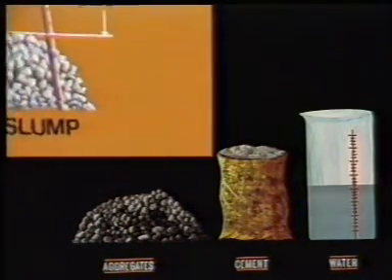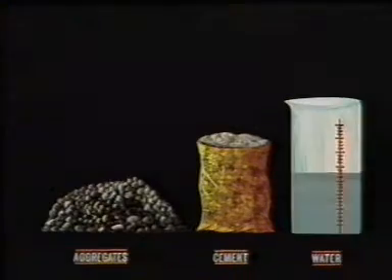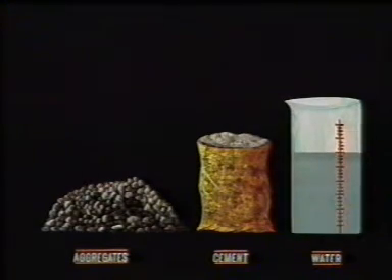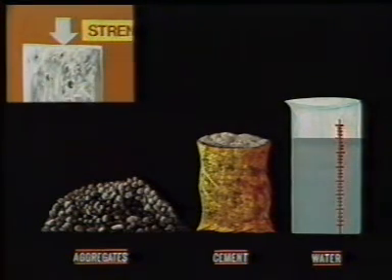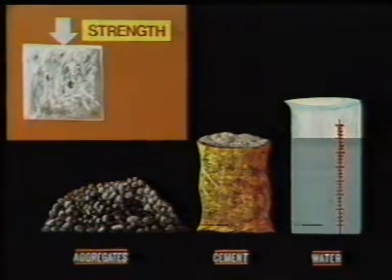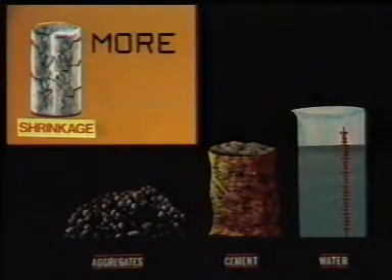The factors such as water content, influencing workability and strength, are contradictory, and therefore to achieve the objectives of mix design, a certain compromise and optimization are required by trial mixes.